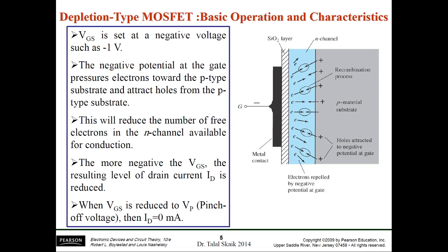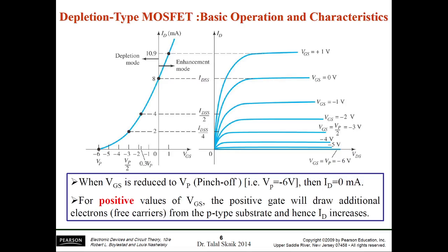Now you will get the concept. So this is the waveform of this. How to read this waveform? First of all, in the depletion mode, if the voltage VGS is 0, you will see the maximum current of 8 milliamperes. That is nothing but IDSS, the maximum current.